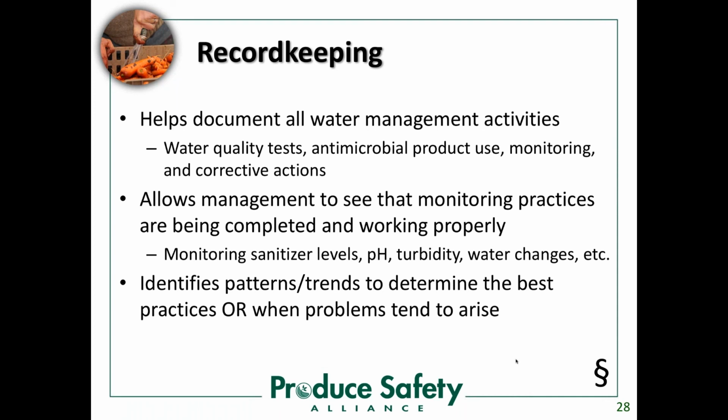Every one of these, I talk about record keeping. Document your water quality test. Anything to do with your antimicrobials, your monitoring, your corrective action, anything to do with water quality, keep a record on it. And that does two things. One, it covers you in case there's a problem, but two, it tells you that you're completing and having effective monitoring practices. Sanitizer levels, pH, turbidity, any change in water, et cetera, et cetera.